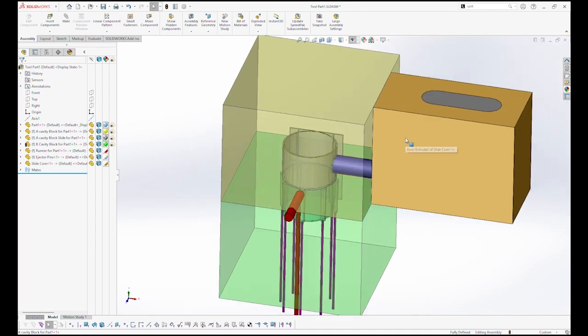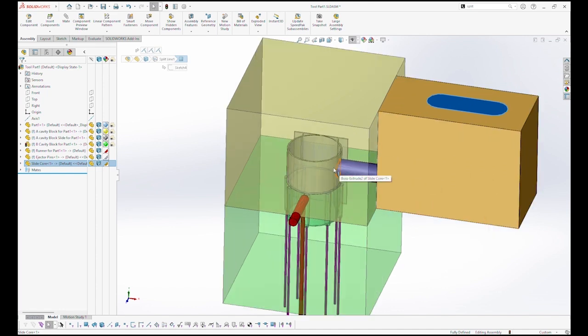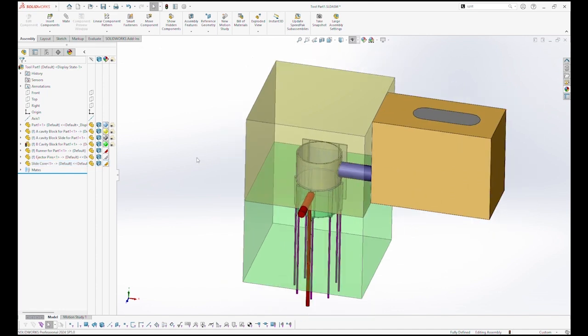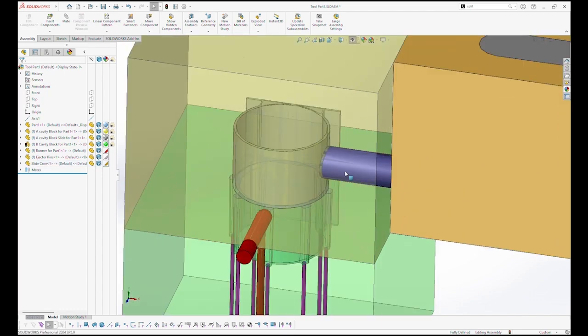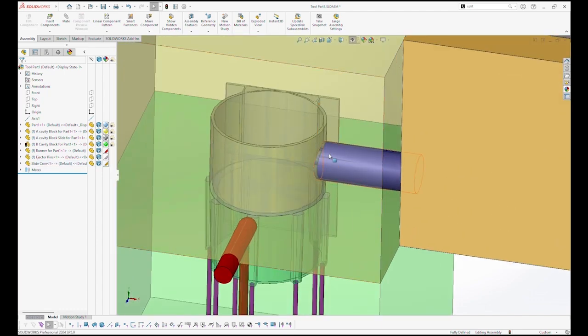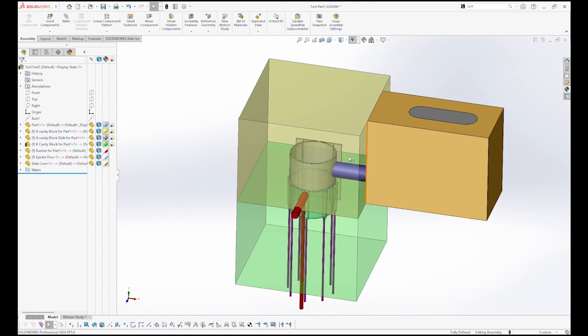And whenever that happens, typically there's a slide system that's actuated mechanically. In this instance, we would have a pin that goes through there, and when the mold opens, that pin would be at an angle and it would push this slide back. And typically, as we open the mold, we slide that slide back, and then we eject after that core pin has cleared that hole. This is a thing that people do all the time, putting either full circles in or just geometry that have an undercut. But that would be an example of a slide and how a geometry feature perpendicular to the axis of the parting line is created.